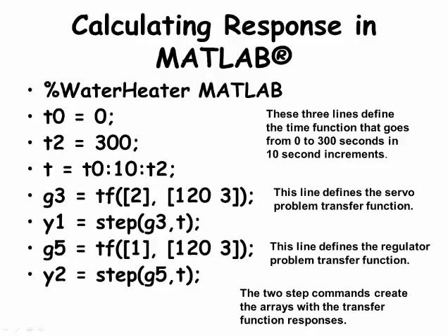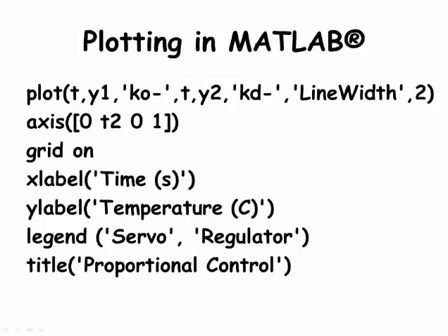Here are some MATLAB commands for a script that creates the time array, defines the servo problem transfer function, defines the regulator problem transfer function, and creates the servo and regulator problem responses to unit step changes. The results are in array Y1 and Y2. These are the two arrays that we will want to plot with a T array that gives us the time steps. Here are the MATLAB commands to plot the servo and regulator problem responses. You may want to review the material in Appendix A and what you did in Lab 4 to help remember what all the commands do.